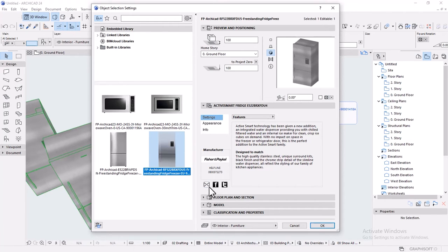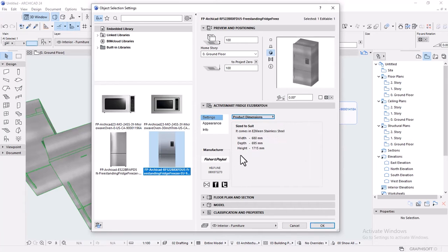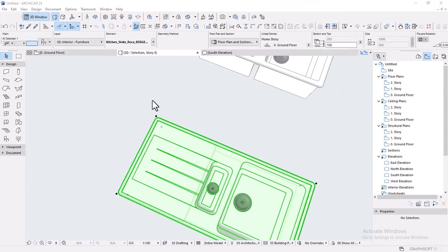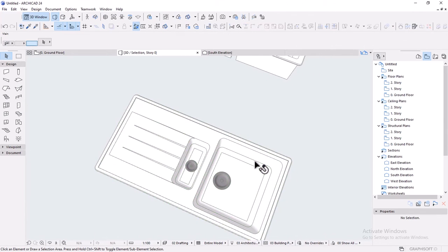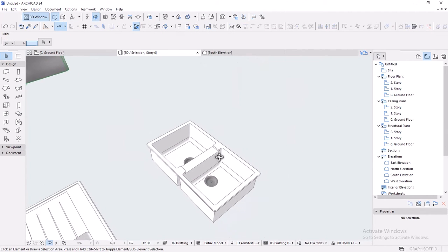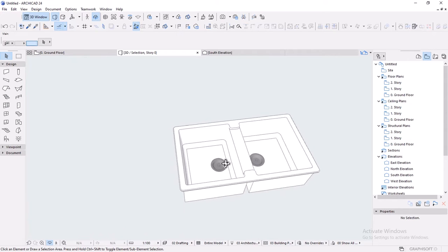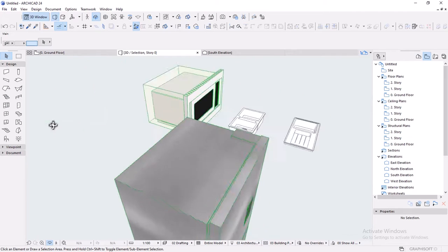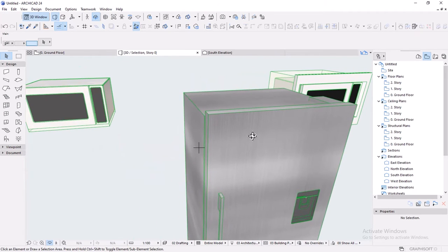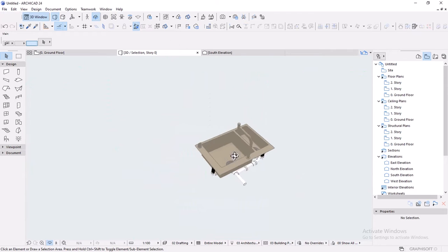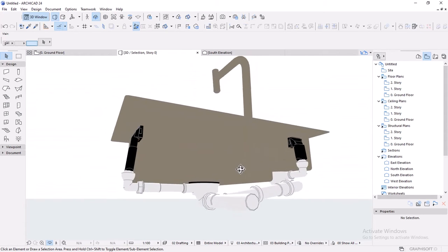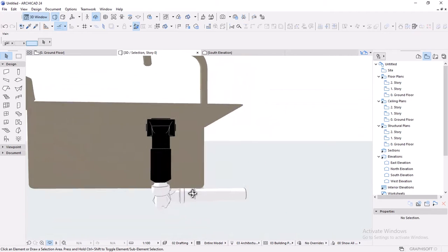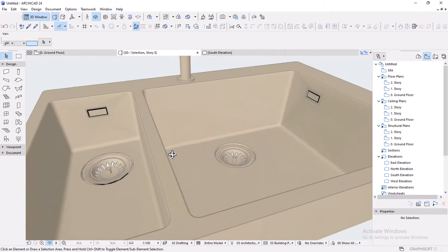A BIM object is an intelligent object which depicts the product or material in a digital world by combining visualization data, metadata, and behavioral data. Often called library objects, they are used during the initial design phase as placeholders, as a visual expression of the need of a specific object to be selected at a later stage. Basically, a BIM object represents the product's physical characteristics in a digital environment where the object behaves as an actual product does in the built asset.